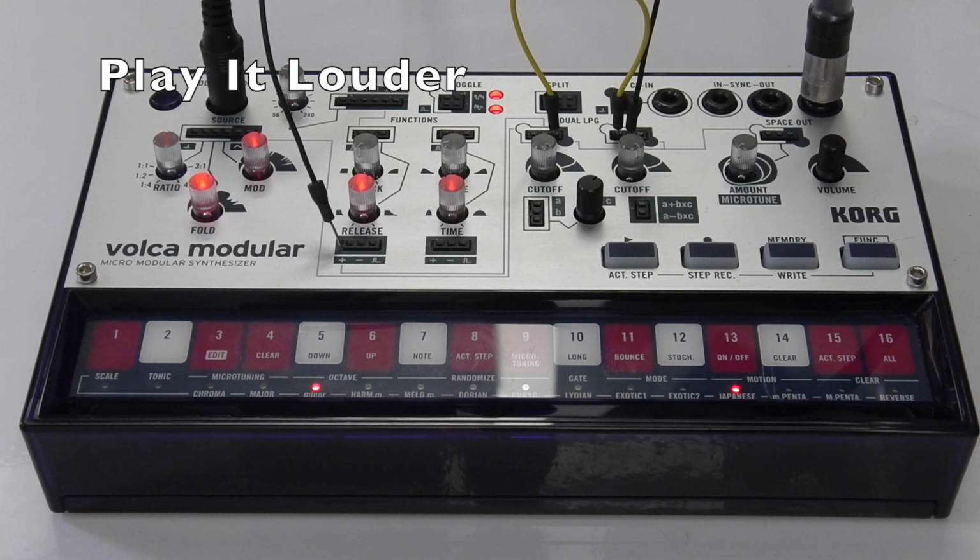However, before we hear anything from LPG2, we need to give LPG2 a volume level. So we're going to duplicate the volume level or the amplitude envelope that we're using from function 1 for the main sound. So we're going to connect the function 1 positive output to the LPG2 level input. When we make this connection, we will hear that the sound is louder because we've duplicated it and we've added the two sounds together, and therefore they're louder.